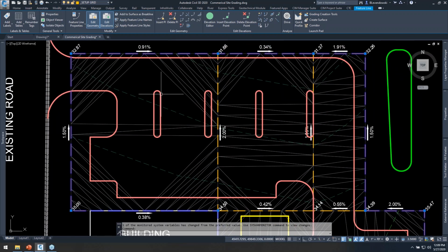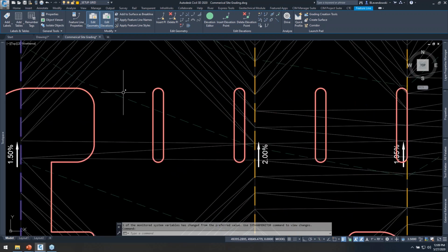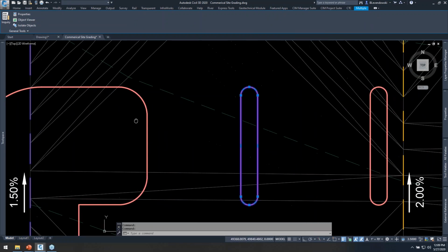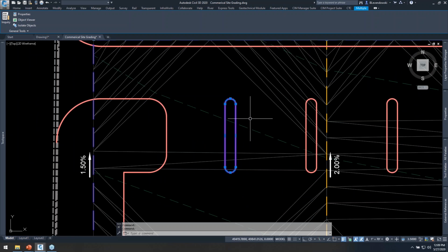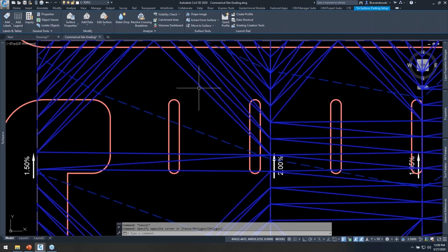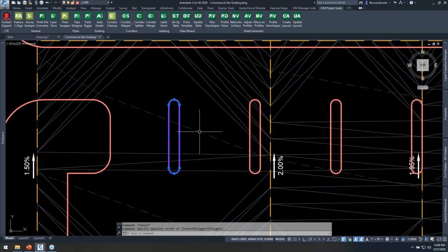The reason we do this is because parking lot grading, the sloping can be fairly simple, but because the horizontal geometry is fairly complex, you end up managing a lot of little elevations across all of your site, right? All these PCs and PTs and all these PIs across all these curb lines, it gets really tedious, right? So if you instead generate a simple surface like this, and then you pull elevations from it, from your curb feature lines, it's a really quick way to assign elevations, okay?